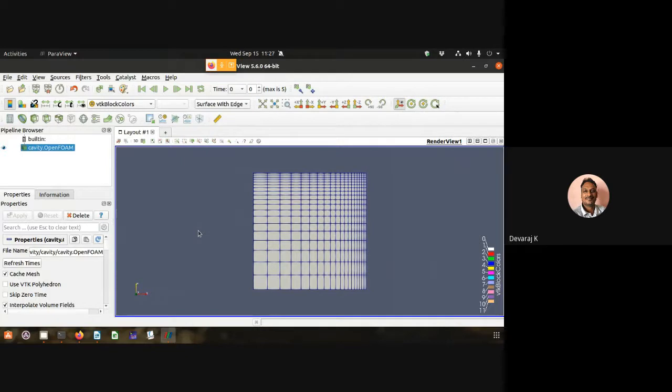Look at this. What has happened? On the right hand side, it is 0.1. That means I could see there is an increment. A refinement is happening in both your positive X and positive Y direction. So I want a refinement to the right hand side. I want it to be refined at the right hand side. So instead of grading 1, I can see I have done 0.1. If you still want finer, I can go with 0.01, or if you have very large, huge volumes, I can go even lower.